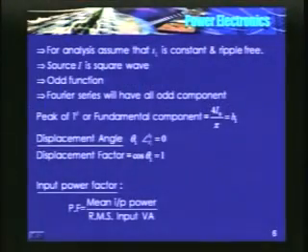I will repeat, it is the fundamental component of the input voltage and the current that are responsible for power transfer. The higher frequency components, all the other odd components, will give rise to additional I square R heating. They do not contribute to power transfer, they contribute only to additional I square R losses.